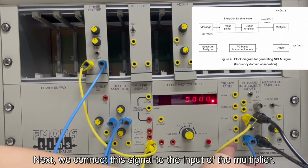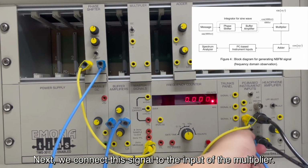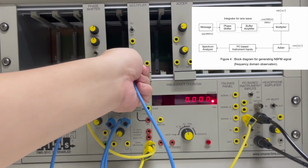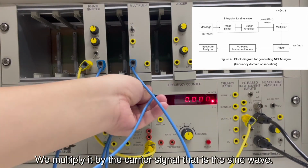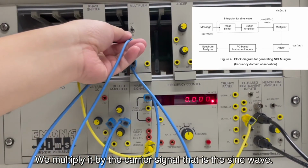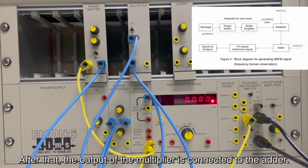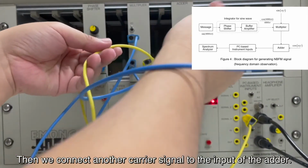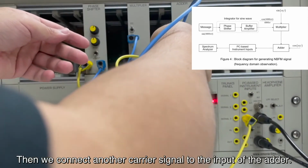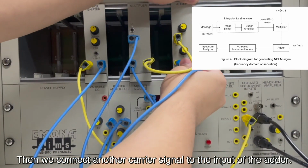Next, we connect this signal to the input of the multiplier. We multiply it by the carrier signal, that is the sine wave. After that, the output of the multiplier is connected to the adder. Then we connect another carrier signal to the input of the adder.